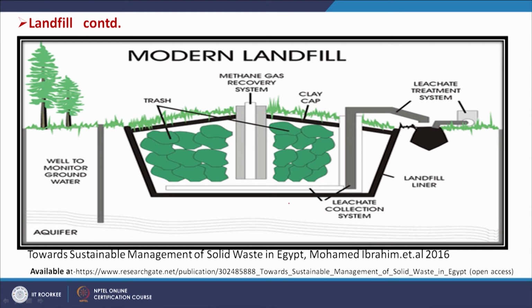So, similar reactions take place as in anaerobic digestion, and this is a modern landfill. Here we see the lining is done for leachate collection, and the landfill liner is shown here, and there is a leachate treatment system. A clay cap is provided at the top, and inside, the trash material is put here, and a methane gas recovery system is also there, where biogas is produced. But this should not be installed near a groundwater well. The groundwater well should be a certain distance away from the landfill site.